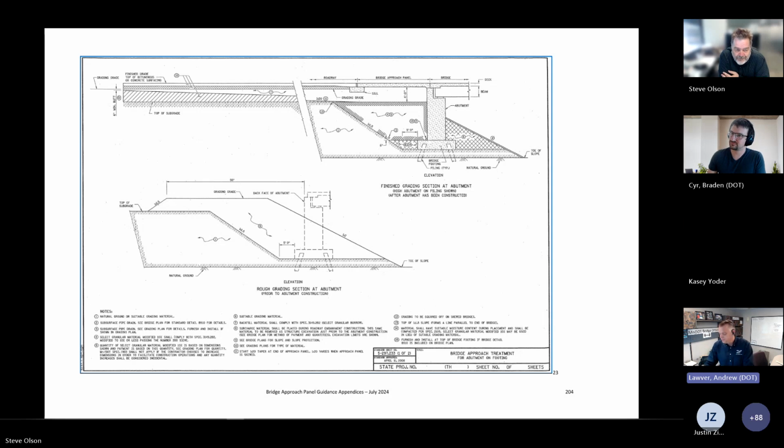We've had some very frustrating experiences with some E8 joints down in D7. Our bridge crews go back after a year or two and find them disintegrated, or not connected and having floated out or dropped down. We met with our construction staff, and one issue was what the brand name was, or what type it was, and what the instructions for installation were, right? So how are our construction inspectors able to inspect something and make sure that it's done according to the manufacturer's instructions if they don't even have those instructions?